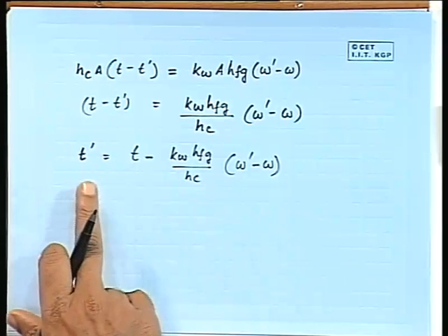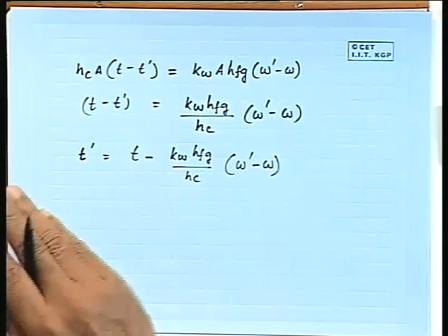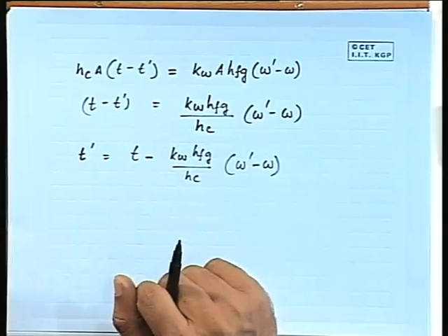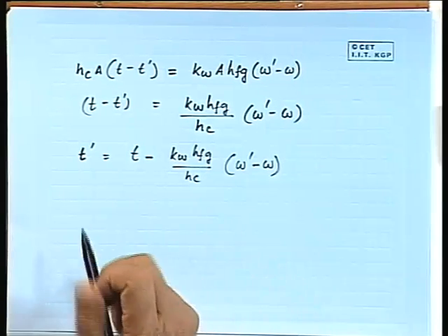That is not needed for this course, but this T dashed then becomes another thermodynamic property for air water mixture. And one can independently measure T dashed and T. Let us say pressure is fixed, that means it is atmospheric pressure. So, three different properties are needed. Any other property of the air water mixture can be determined, and that is what we do with the help of a psychrometric chart.